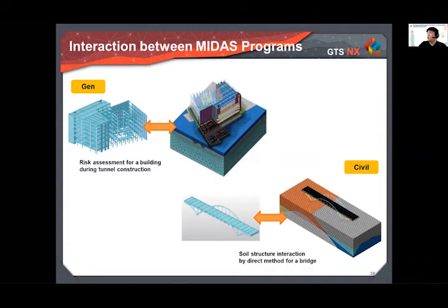Generally, in geotechnical software you can simply apply a pressure load or point load to simulate the building. But in that case, you cannot check the deformation behavior of the structure during the excavation. So this is the only way to check the deformation or behavior of the structure buildings during tunnel excavation in geotechnical software, including real building structure modeling.